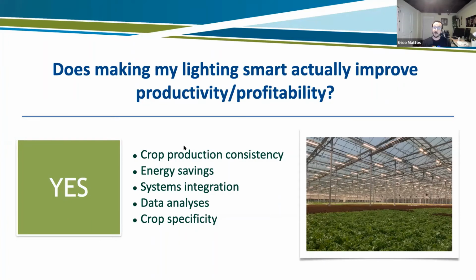If you can do that, you will realize energy savings. So if you're ensuring consistency during the dark months of the year, you can definitely realize energy savings when you have more sunlight available. You have months or days in which your lighting is going up and down, and you're going to be over-illuminating if you don't have a smart control system. By sensing that, you provide lighting just when it's necessary and you save energy that way.